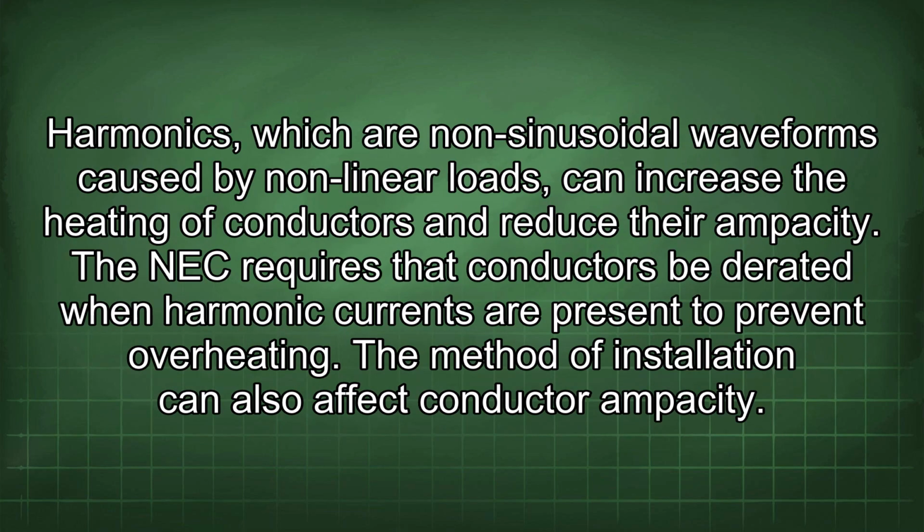Harmonics, which are non-sinusoidal waveforms caused by nonlinear loads, can increase the heating of conductors and reduce their ampacity. The NEC requires that conductors be derated when harmonic currents are present to prevent overheating.